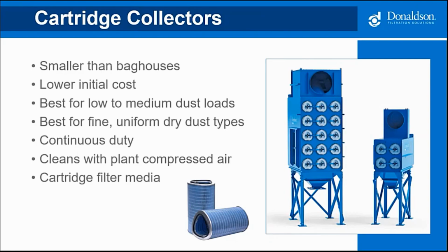Number one, it's going to be a smaller footprint than a bag house. Thus, the cost is going to be lower. The application for weld fume is typically 2 grains per dry standard cubic foot or less. So we have a very low dust loading on the application. Plus, this is a very fine submicron particulate. It's usually uniform, spherical in shape, and it's, again, ideal for cartridge technology.